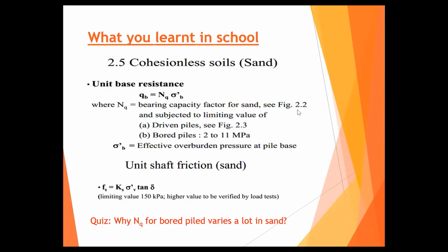So it really depends on the workmanship, especially in sand, because once you excavate the soil in sand, the overburden is relieved, you will tend to have some disturbance at the bottom, especially in a country where the groundwater level is so high. So it's natural that the end bearing is very difficult to control.